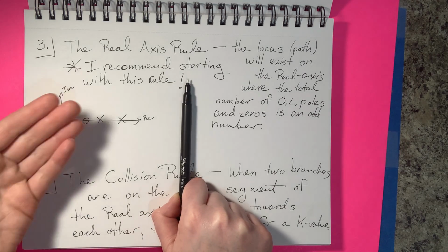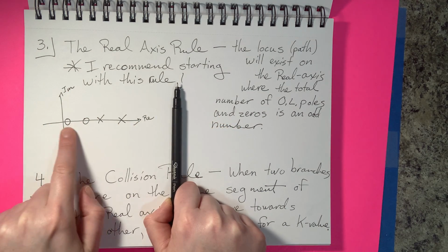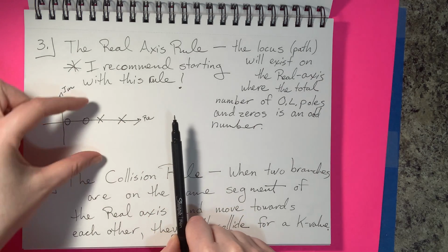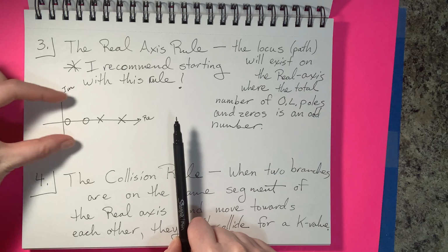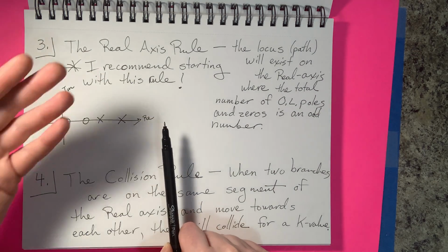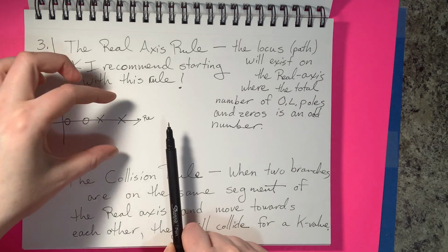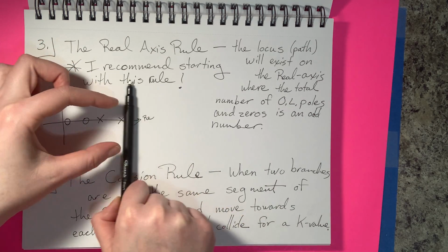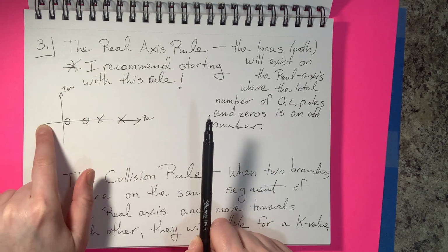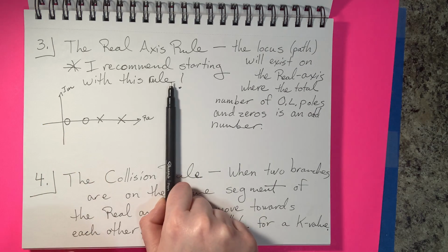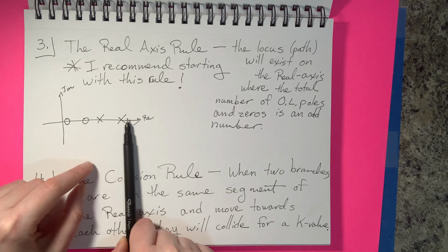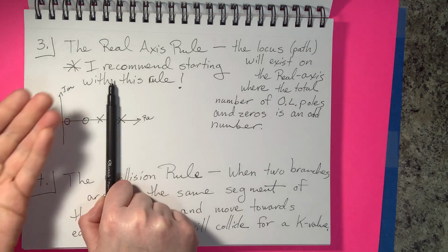So you do this and you count the number of elements that you have, and they have to be on the real axis. You can't have a complex axis or imaginary parts counting towards this. Now if you do, it really doesn't matter because you're adding 2 at a time whenever you cross a point, but just notice that all you have to do is count what's on the real axis. Okay, so we move our pencil across here and we look rightward and we count the number of things that we pass that we have on the right.